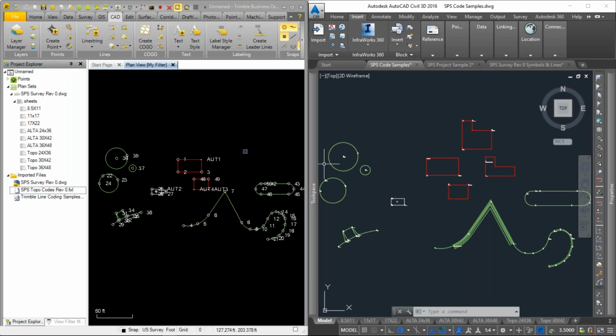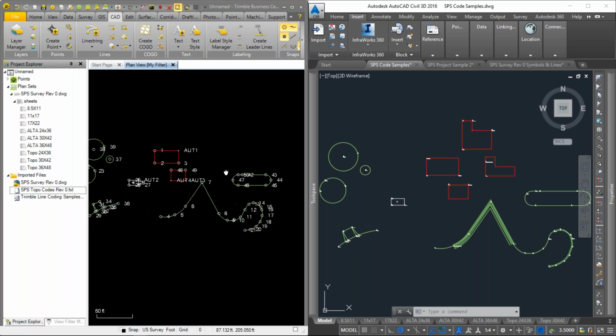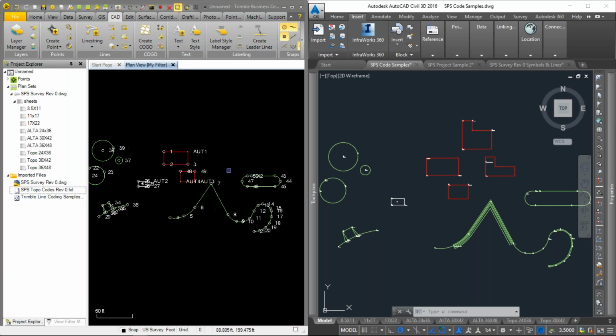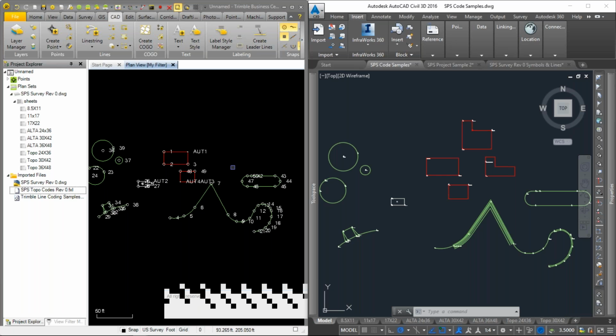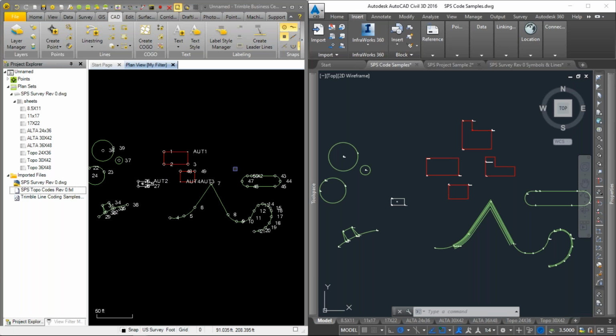So I'm sure everybody is thinking there's a couple of rectangles that aren't up there, a couple, call them rectangles, polygons. So is that due to the field collection method? Like you're saying the codes are slightly different? It is partially due to the field collection method and partially due to the available line control codes. Okay. There are a couple of additional codes in Civil, so you can use them. You can still enter them in your data collector as you would. They just process slightly different in TBC, and some of those are also being looked at. Essentially, it's an extend command and a right turn command and a recall that are different.